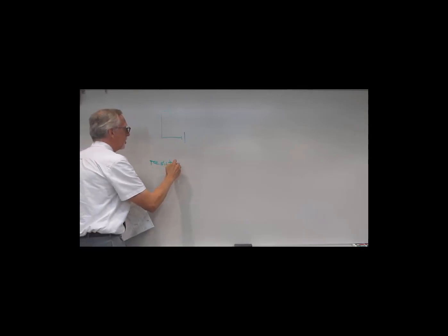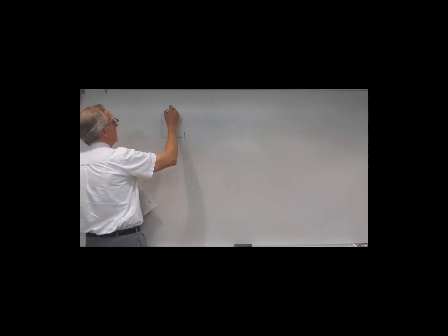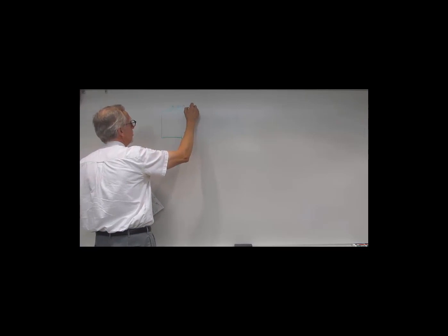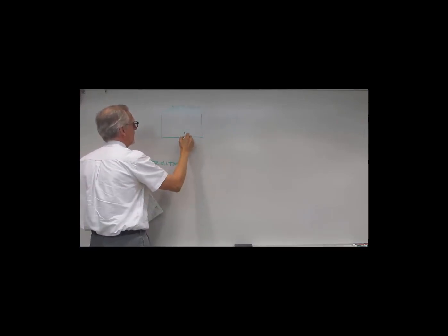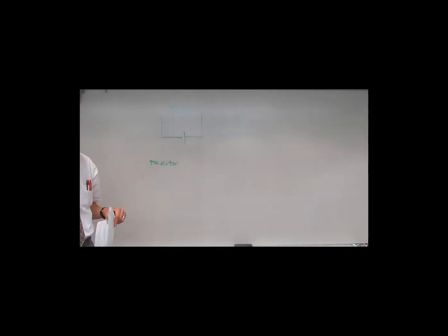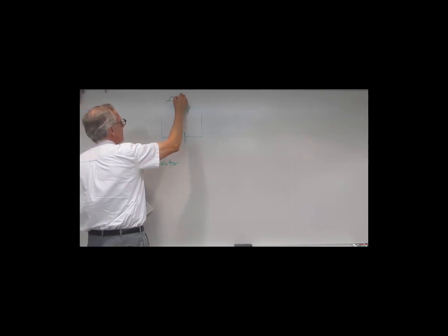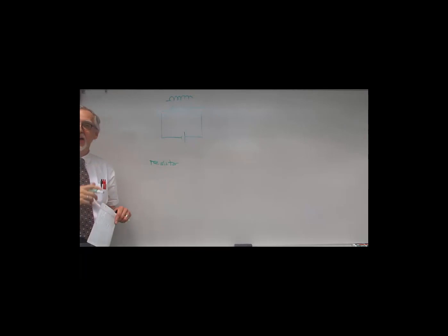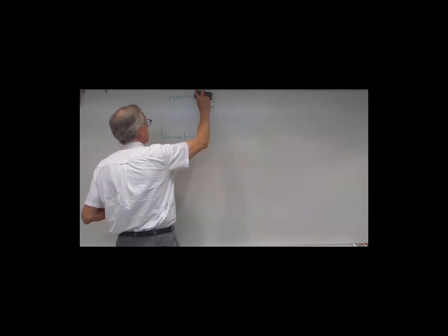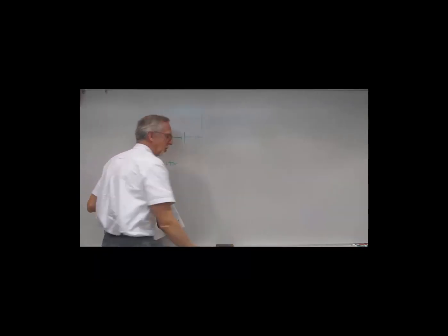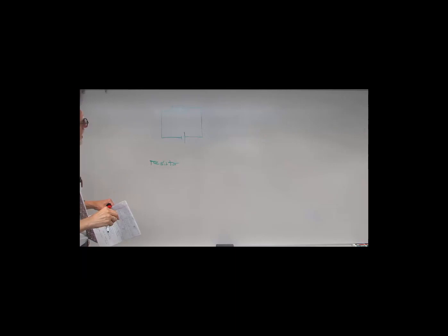The symbol that we will use for a resistor is a sharp sawtooth little thing like that. Now, when drawing it, be careful, make sure you make it a sharp tooth thing, because if you get kind of sloppy and do something like that, a little spring-shaped thing, that actually is the symbol for something else that we'll see later on, an inductor. So make sure that you have a nice sharp-toothed image.